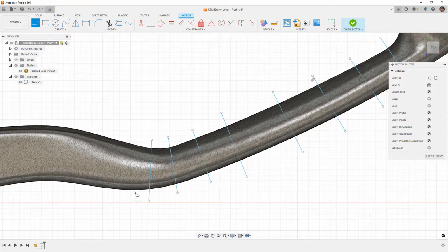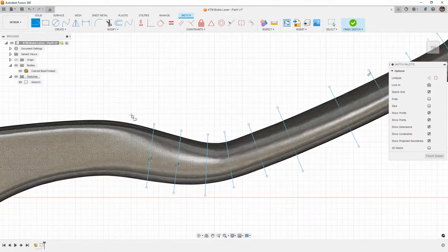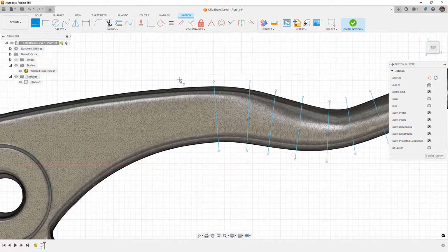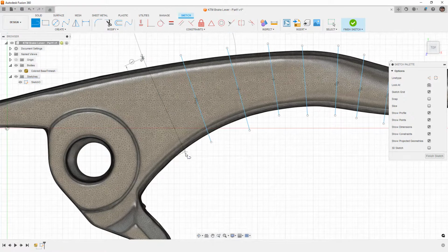And generally, if we're going to use lofting to go through these different sections, we're not going to have any guide curves. There will be no guide rails because all it's going to do is make this geometry pretty bad. Since we know that we have this reference here, lofting through this many sections is probably going to be fine. The geometry we get is probably okay, but you do still need to be very careful about it. So I'm going to come over here fairly far.